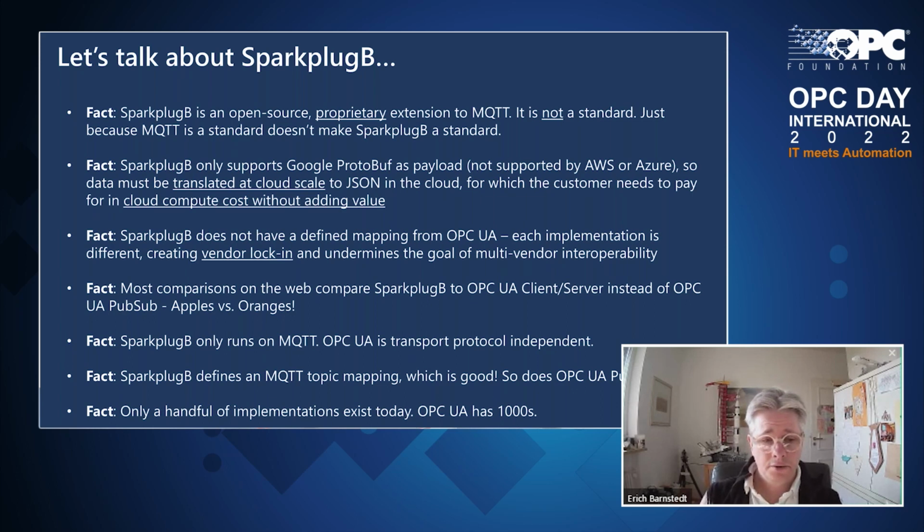And then another thing is, converting the data on the shop floor is also required, because obviously a lot of times data comes from all sorts of different machines. So you're converting it to OPC UA, or in the case of Sparkplug-B, you may be converting it from OPC UA. Well, that conversion is not defined, right?